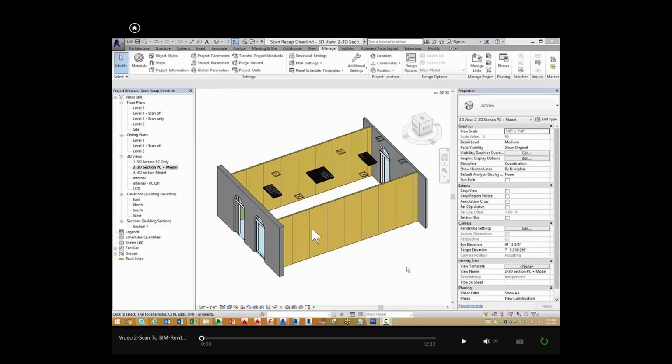Now, using another product called Autodesk Point Layout, I had control points that were in the room, and I placed them in the Revit model. Those control points had coordinates associated with them. I gave Thad a text file that just had 3 lines of text. It had those 3 points and their X, Y, Z coordinates. He put them into a scanner, so now when he set up his scanner in the room, he told it where it was in space.